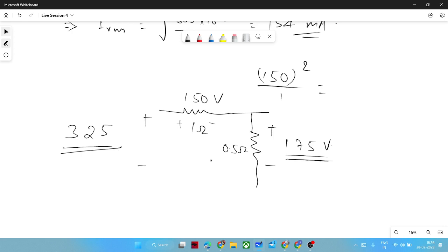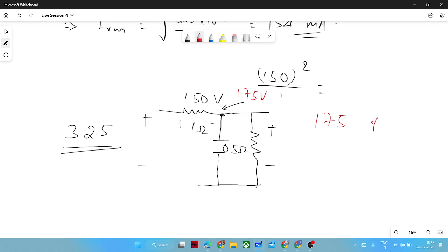Yes, you are correct. In that case, your capacitor will be in between, so at the capacitor you will see a peak of 175 volts. Your supply has been reduced from 325 to 175, so your peak capacitor voltage is itself now 175. So your output voltage will vary from 175 to 175 minus delta V, the ripple. Right?